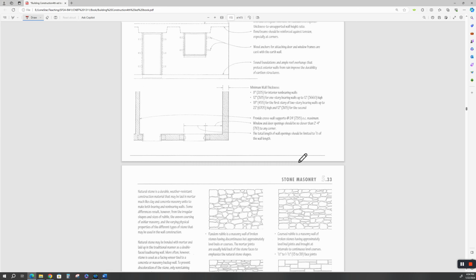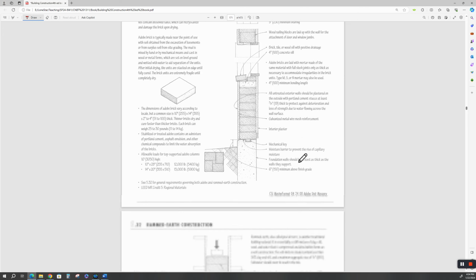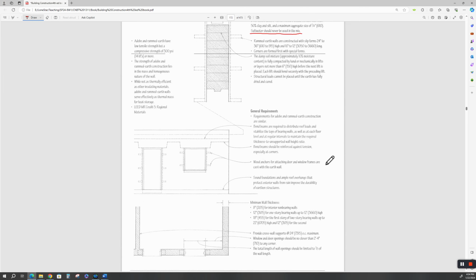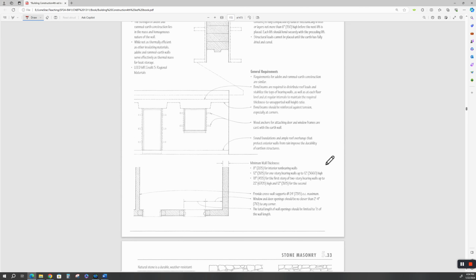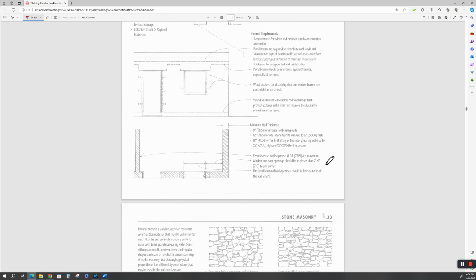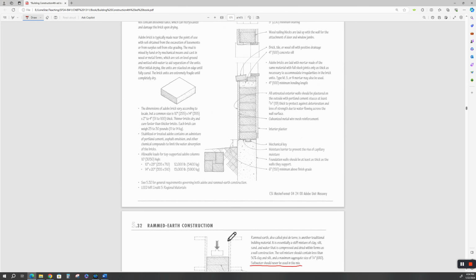So I'm not going to tell you adobe or rammed earth unless you want to be tested, but I'm not. Now, if you can get by with this in the climate you're in, then fine. An adobe structure or a rammed earth structure, if the walls will stay together, maintain heat really well. But so does a concrete block house. If you do two wides instead of adobe, you do two wides of typical CMUs.